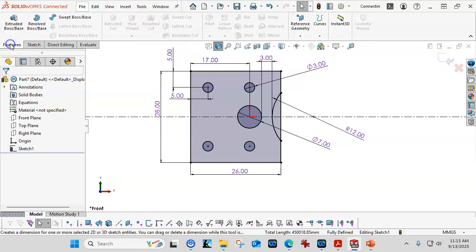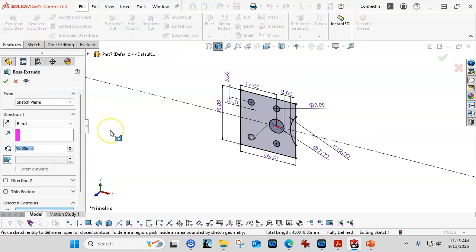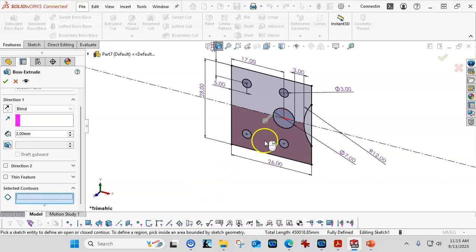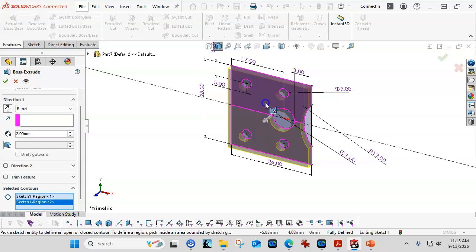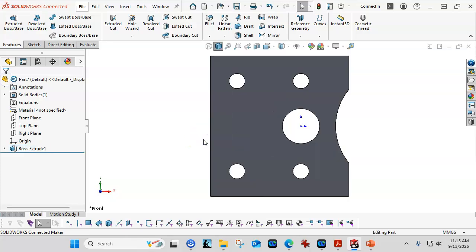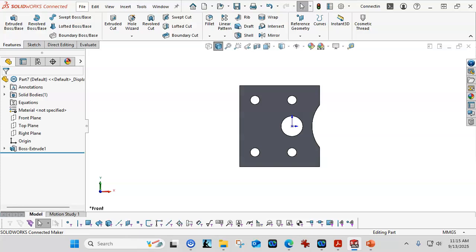So let's go into the extrude, and this being that infinite length center line, this is one of the places that if we have to do, yeah, we'll probably have to do the contour and regions because I have those multiple items. That infinite length center line is participating, so I do need to make 2 selections. I don't want to go to the contour because then I'm just going to get pretty much the whole box. That doesn't really help me here. So we go ahead and hit accept, and we have our geometry.